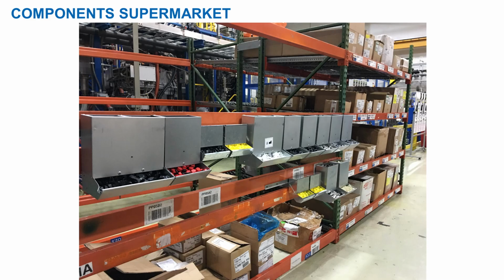This project was enormous, resulting in hundreds of corrective actions as part of the improve phase. Part of it was that I established line side and point of use storage for all the components. And this was a supermarket, and these containers are actually animal feeders, but they work great for this purpose.